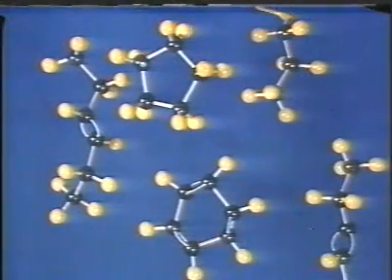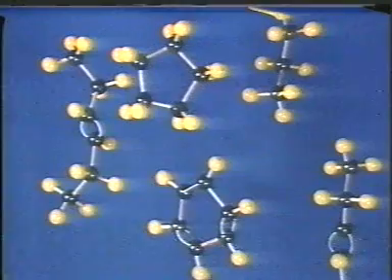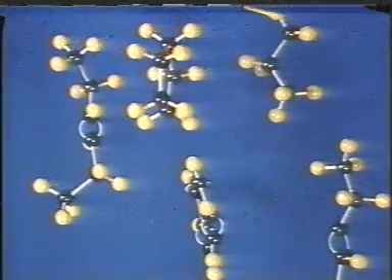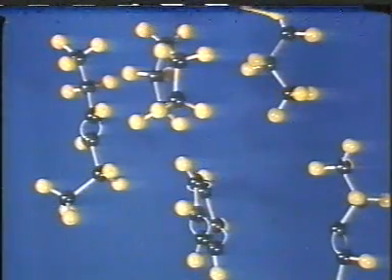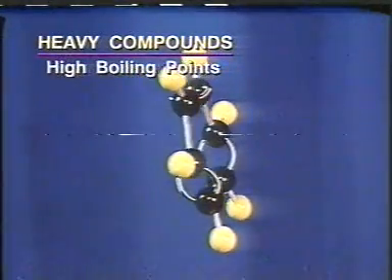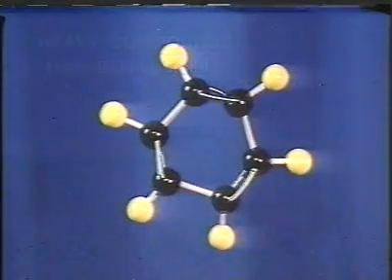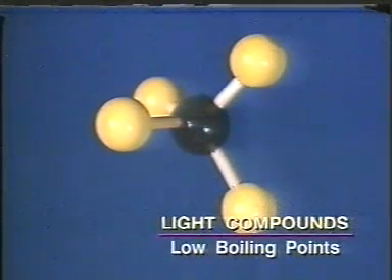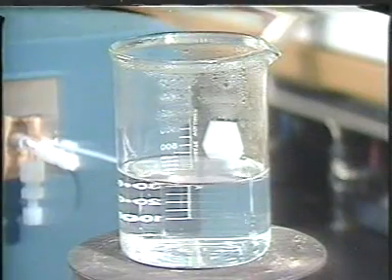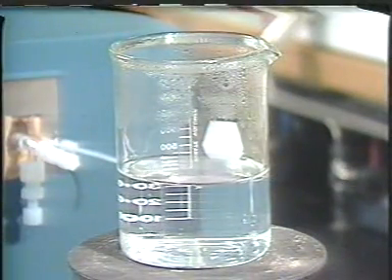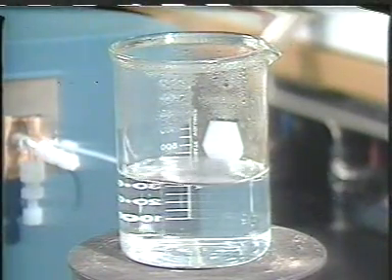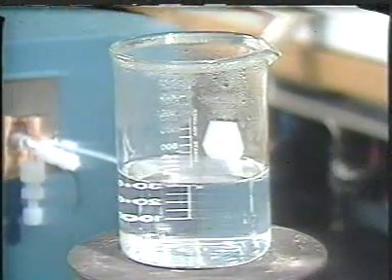The properties of various substances are determined to a large extent by the size and structure of their molecules. In distillation, the property we're most concerned with is boiling temperature. Substances composed of large, heavy molecules tend to boil at high temperatures, while smaller, lighter compounds have lower boiling points. Distillation uses heat to separate a mixture of different compounds by their respective boiling points, or boiling point ranges. Let's see how this works.